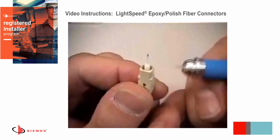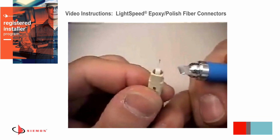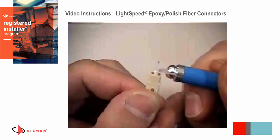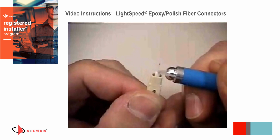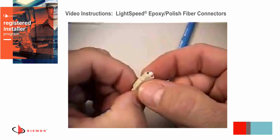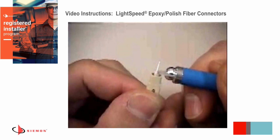Carefully score the fiber on one side close to the intersection of the ferrule tip and fiber. Do not use excess pressure, to prevent fiber breakage and uneven fractures. If the fiber stub breaks off during the scoring process, you may continue with the polishing process, but it is possible that the glass may have fractured down into the ferrule tip slightly. Inspection with the microscope after polishing will reveal this result.